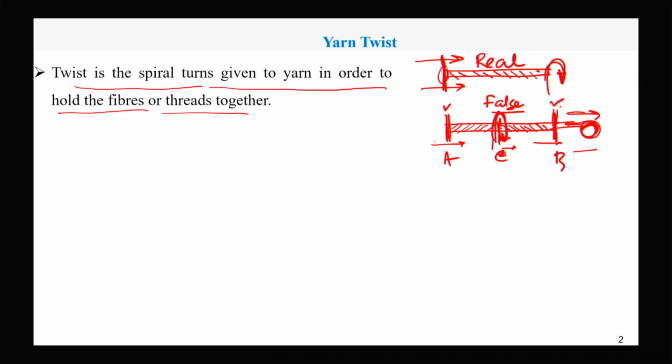So this rotation at the middle is continuing, and suppose this is the positive side and this is the negative side of twist of the same extent, and while moving with linear movement, as soon as it's crossing the point C, the rotational point, the negative twist present in the left side of this strand will be superimposed on the positive twist in the right side, and finally this will get cancelled, and finally we will get a strand without any twist.